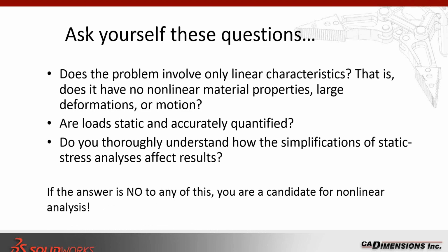So next time, before you run your simulation analysis, ask yourself these questions. Does the problem involve only linear characteristics? That is, does it have no nonlinear material properties, large deformations, or motion? Secondly, are all the loads static and accurately quantified? If your loads are starting to move in a different direction, the load that you apply might not move in a different direction, however, due to the displacement of your part, that load might need to change directions.